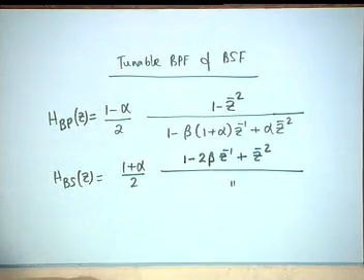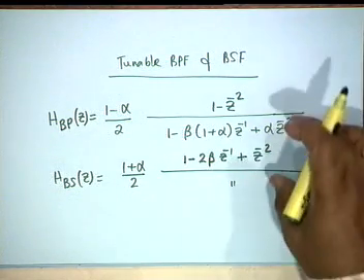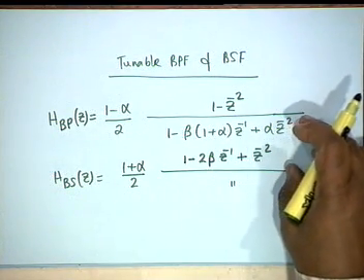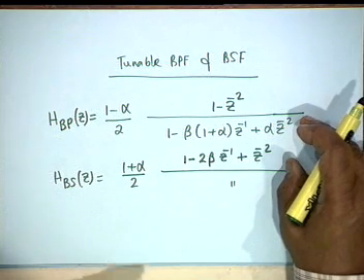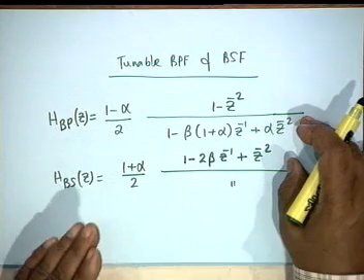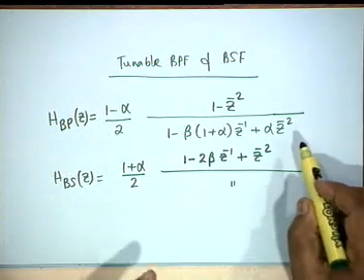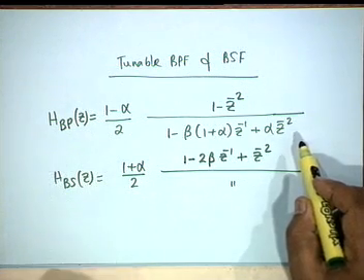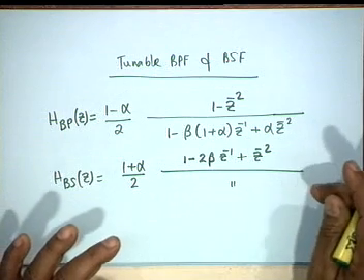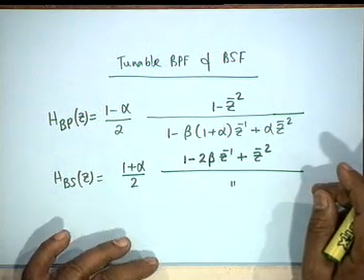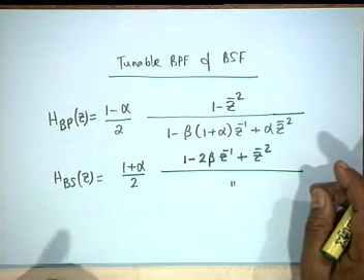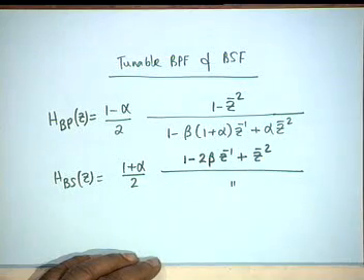We shall show that these are also complementary, doubly complementary, all pass as well as power complementary. Okay. So, we shall show that these 2 filters can also be realized in a single chip using only one second order all pass filter, with the denominator the same as this.